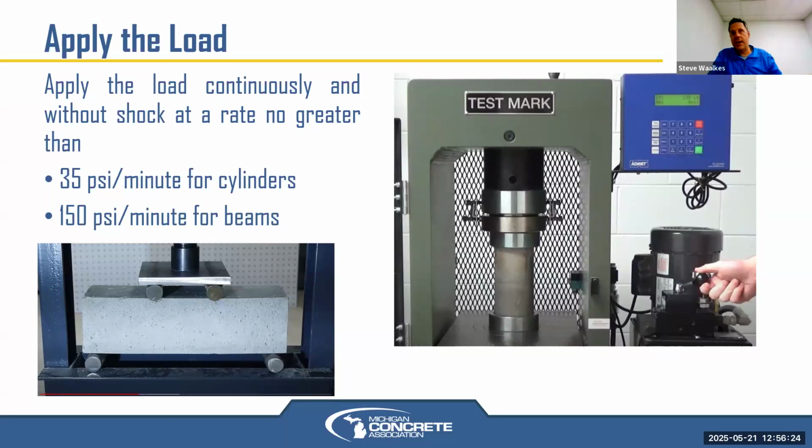Did you get on it? Was it a floor slab that you got on it with a ride-on power trowel, and put a lot of finishing effort into that floor slab and burn the surface and really densified it through that finishing, which is fine. It's not air entrained, but that makes it a very strong surface.